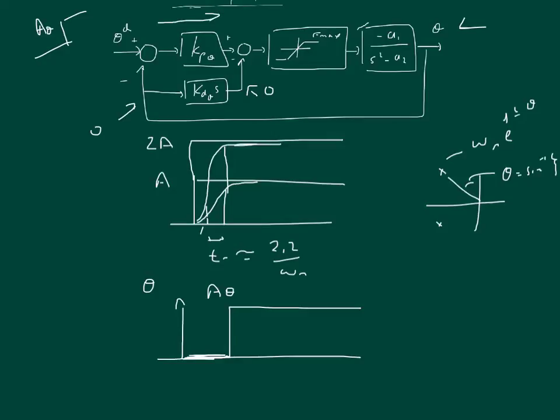And so we can say that the force, F, is going to be equal to Kp theta times A theta. The idea is that for a step size of A theta, if this is the maximum step size we might see, then we make this equality hold where F is equal to F max.